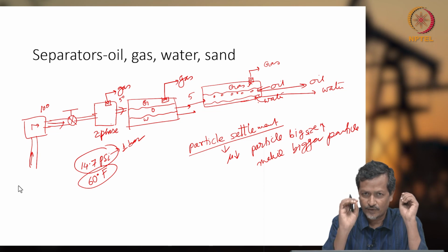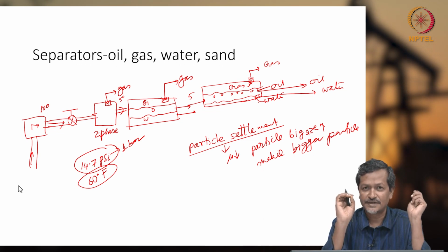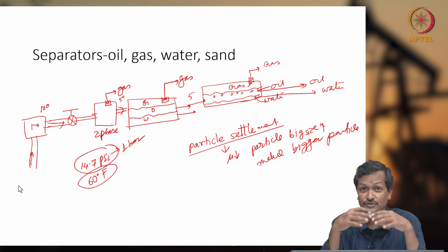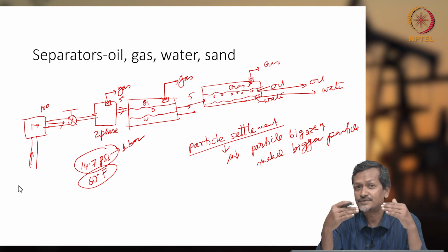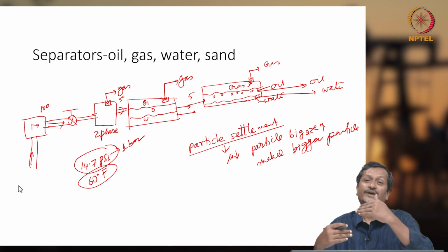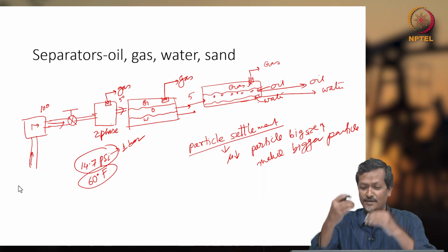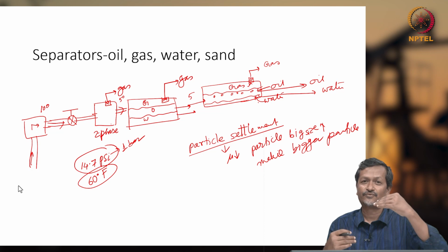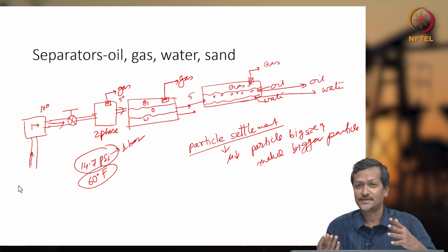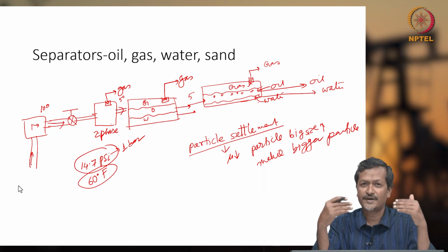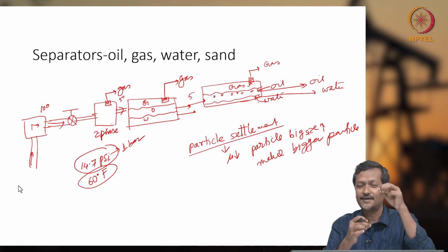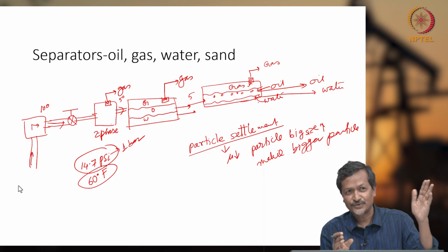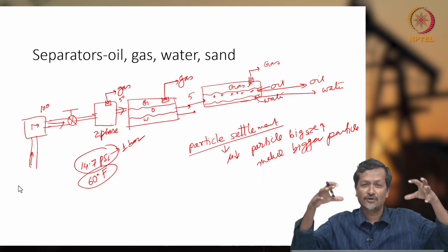You have to lower viscosity, you have to increase particle size, you have to increase collision rate, so the particle size will be increasing. In that way you can speed up settlement, or you can increase flow rate actually. Okay. So settlement will be quicker, flow rate increases, so your productivity will be increasing. And if your settlement rate, or the time taken to settle a certain particle, is high, in that case your flow rate must be lower, so that the fluid will be staying a longer time